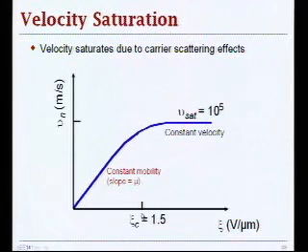That's obviously a property of your material, and for the NMOS, this is about 1 to 5 volts per micrometer. So we assume that we have quarter micron technology, and then we have a critical electric field of 2 volts per micron. If you have a quarter micron channel, you have your velocity saturation occurring at 0.5 volts.